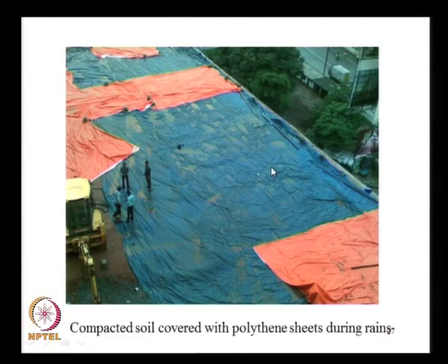And it is also very important that during the construction, if there is any rain, we should not allow the rainwater to percolate, because during construction the soil is just compacted and may not have gained strength.